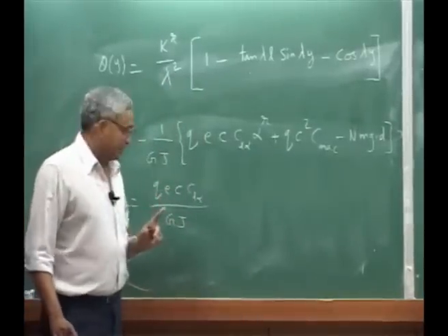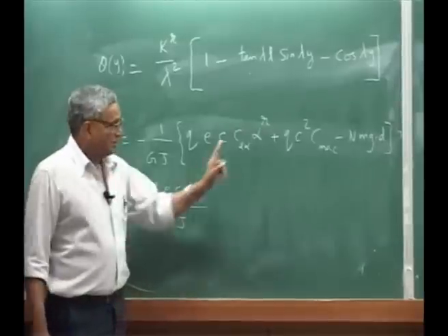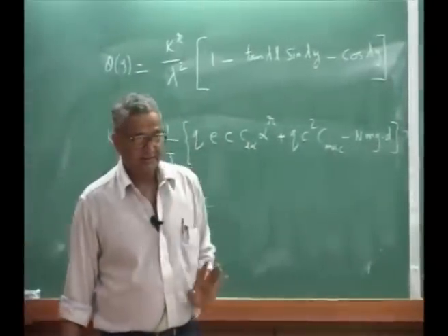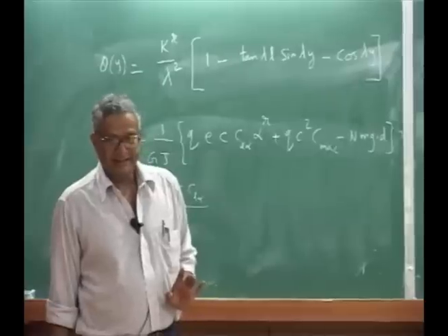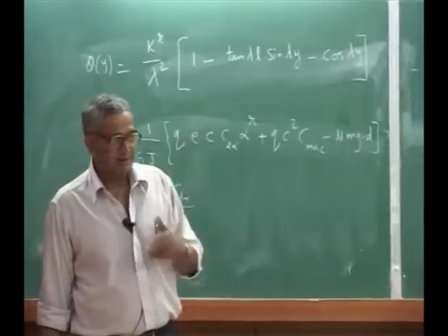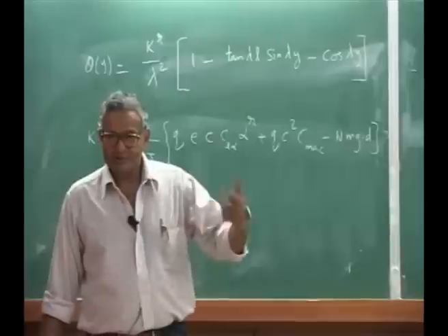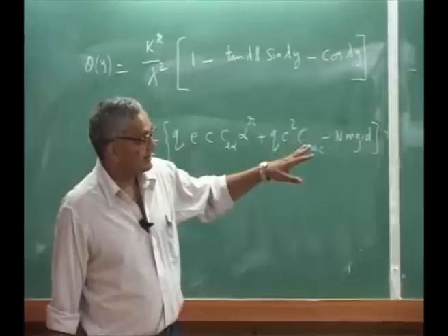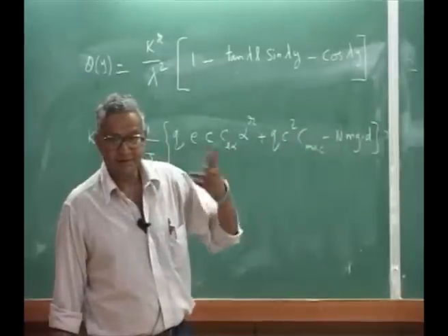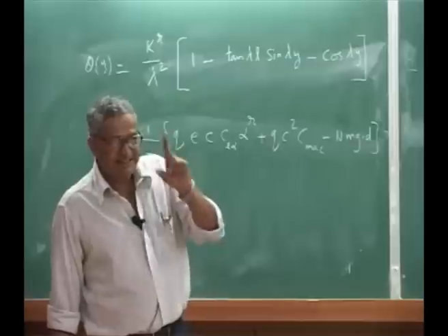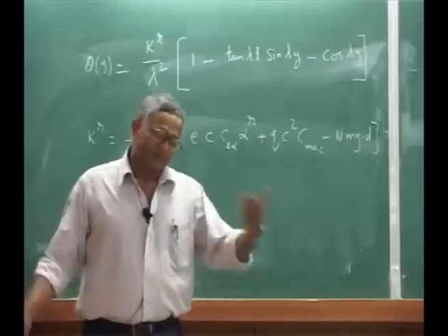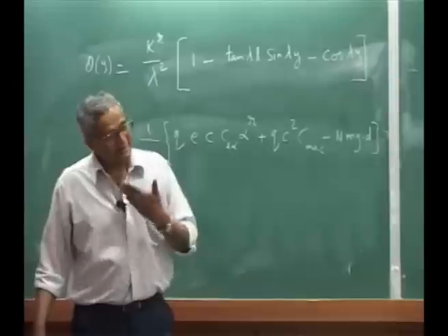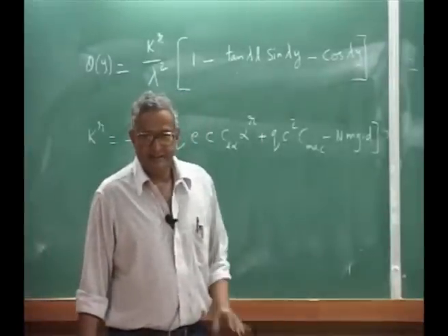Even though you may have, your location of elastic axis, location of mass center, everything can change. You follow? That is why it is an iterative process. You cannot just say one shot solution. Once you design, then you again recalculate, and this you have to do for various flight conditions. That means in the design you take the critical flight condition and design for that. For the rest of the flight conditions, you simply take whatever is the E and D, and then you get the load distribution. Okay? Is it clear?